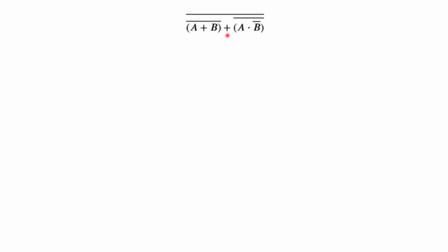We can break that bar and substitute this OR with an AND. So let's do that. See here? From that we got that. We broke that bar, and we changed it into the AND instead of OR right here. So now we have this expression right here, and this expression right here with this bar broken.